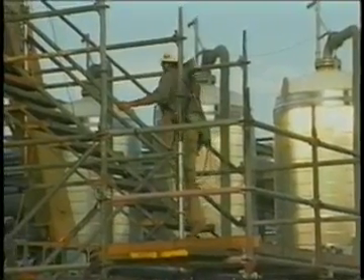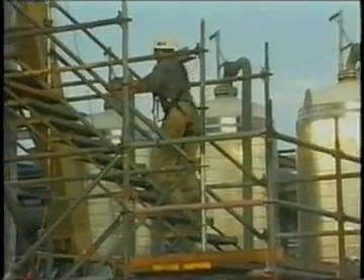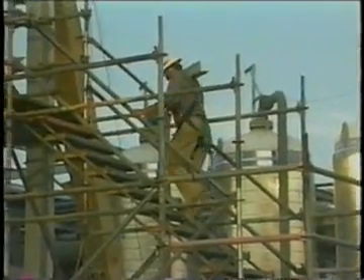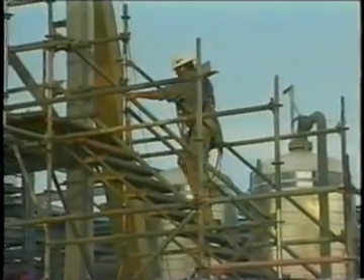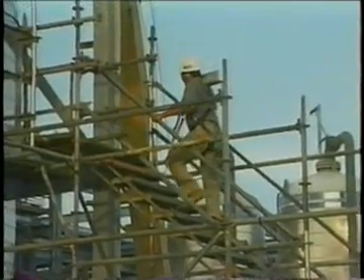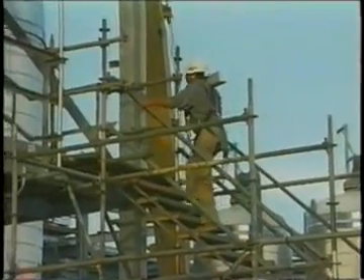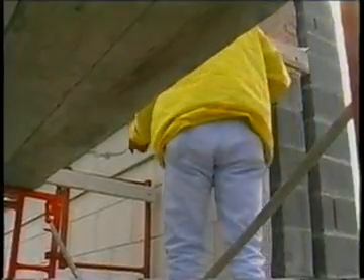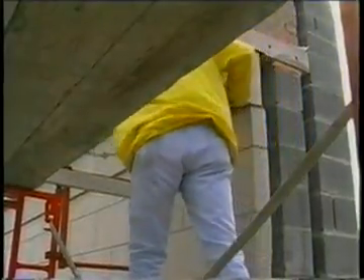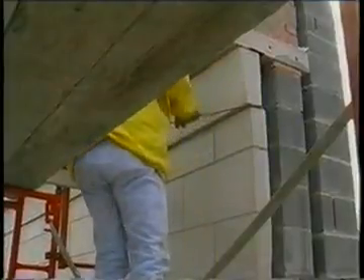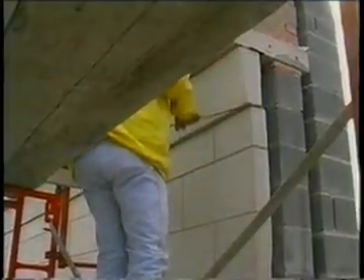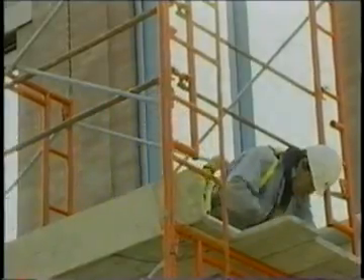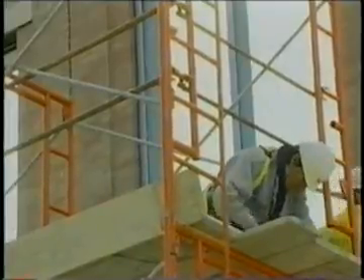When the platform is more than 2 feet above or below a point of access, there must be a ramp or walkway or direct access from another scaffold, structure, personnel hoist, or similar surface. On suspension scaffolds, the competent person must check the scaffold support devices, tiebacks, hoisting equipment, and connections for proper strength and to prevent sway. As we mentioned, fatal injuries from scaffolds were most often due to planking that slipped or